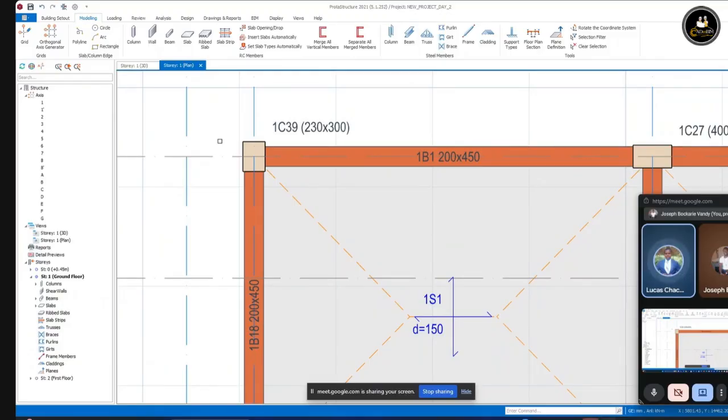at the left side, it's hinged, yes, it's hinged to that place. But if you don't tell the software that end should be hinged, it will assume it as a fixed end. So you should try to define the end conditions of your beams. The advantage of that is that, one, it helps in saving some reinforcement, because you need lesser reinforcement at that point, unlike when it is at a fixed